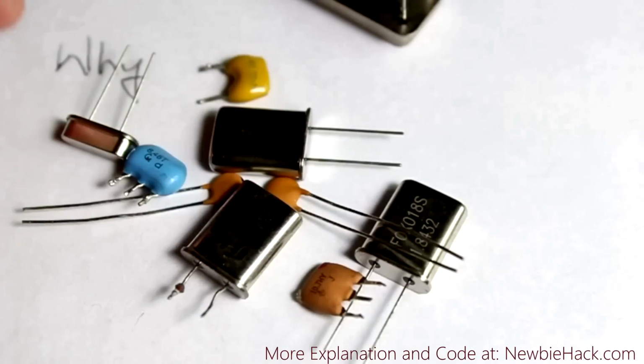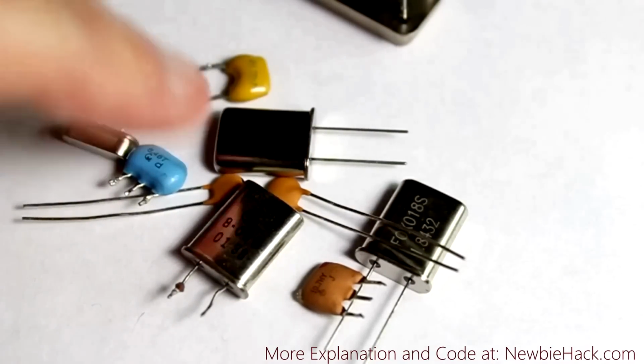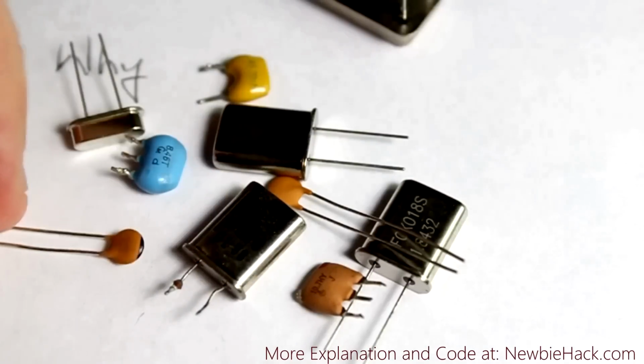I don't know what I have on my breadboard, and it's going to be changing from the breadboard to the PCB, so I'm not going to use any formulas or anything to select the capacitors. I'm just going to use what is recommended in the data sheet and within the range. The closer you get to the actual capacitance you need will give you a better and more stable circuit and more stable frequency. So it's best when after you design your PCB, you can measure that and also get the data sheet for the crystal and determine what capacitance you need for the crystal. A good rule of thumb is just to use a 22 picofarad capacitor.